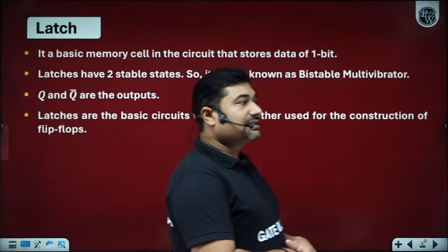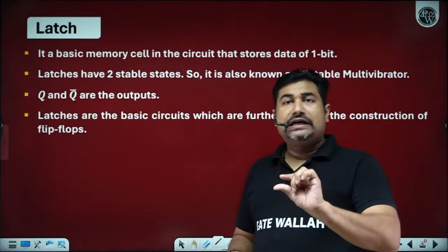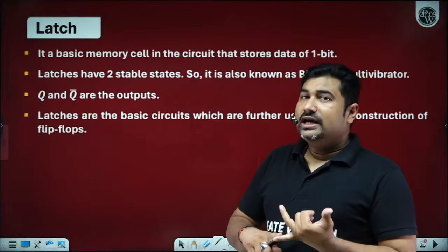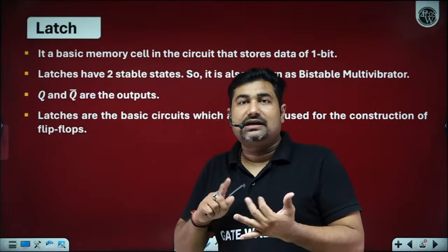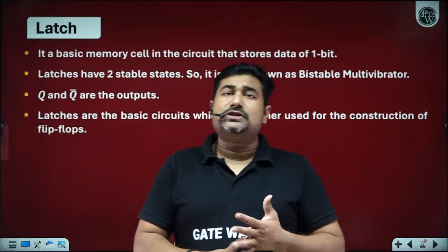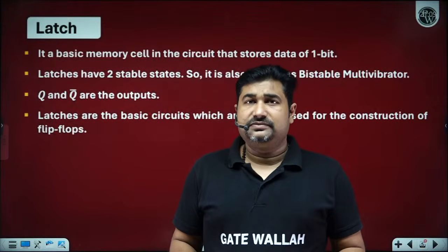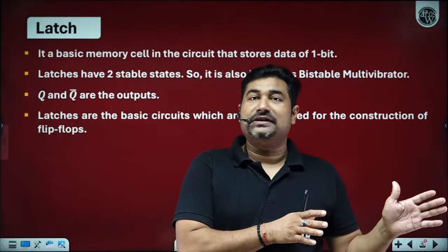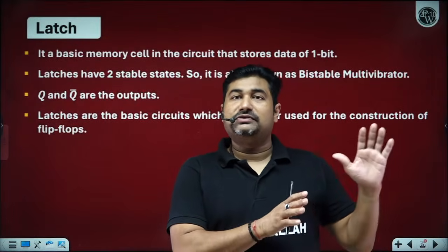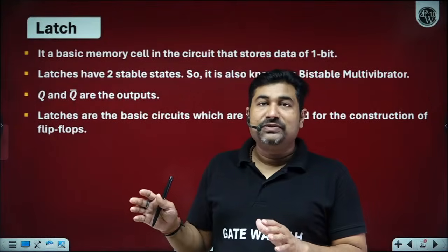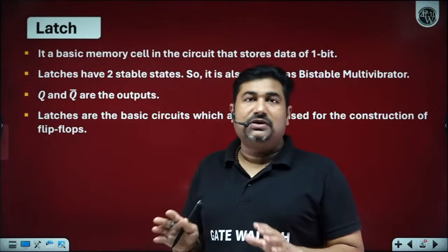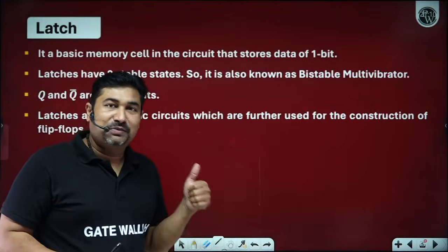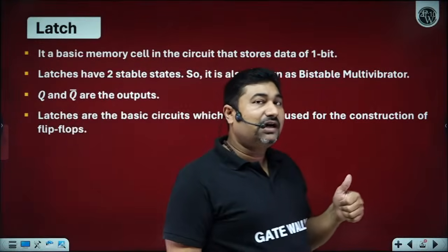Now let's have a discussion on latch. The smallest unit of your entire sequential circuit is the latch. If you are able to understand the latch, you can easily understand flip-flops. If you are able to understand flip-flops, then registers, counters, finite state machines all will become very easy for you, because everything contains flip-flops. To solve any kind of question, whether asynchronous counters, synchronous counters, or state machines like Mealy and Moore, we have to follow only one thumb rule. Before applying the clock pulse, first find the input to the flip-flop, then apply the clock pulse and follow the truth table.